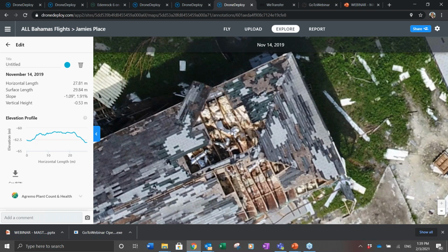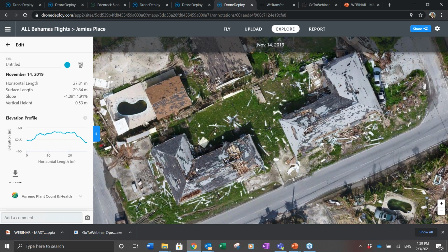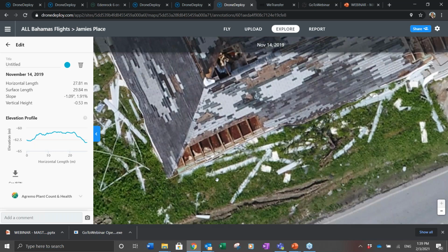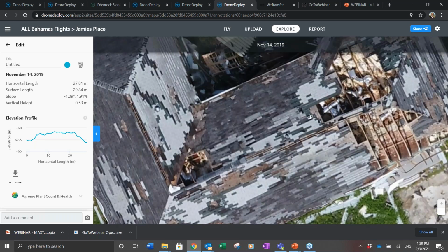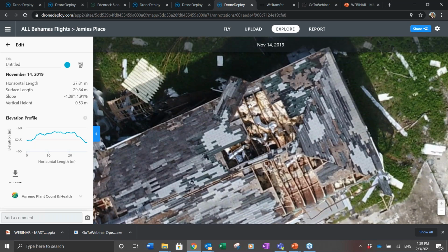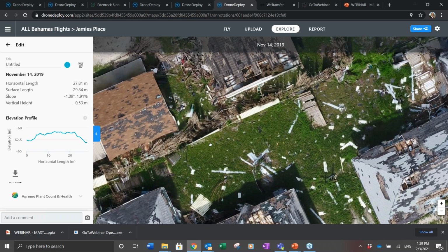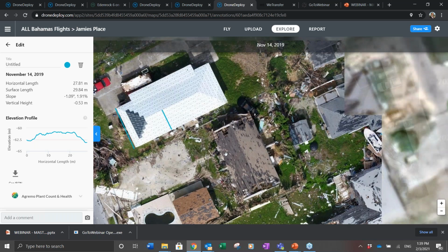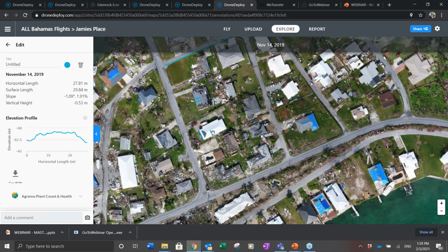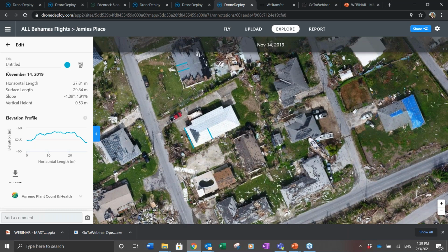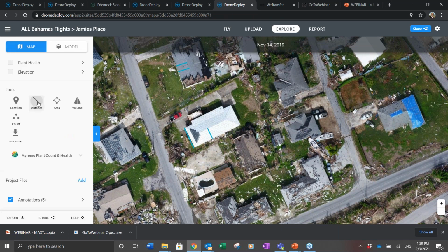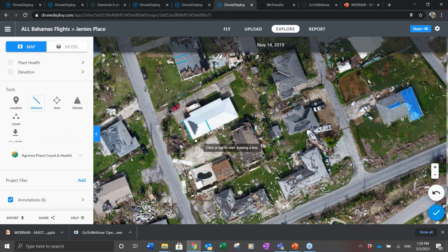Right, so it depends on the lens on the aircraft. You can use, say, a Phantom 4, but you won't get this type of resolution. This particular drone I flew was called a Matrice 210. The optic camera on it had an X5 camera. The cinematic drone we use for origin and cause, one of them is an Inspire 2. The lens on that is unsurpassed. So the details really come down to the lens and the camera that you're using on the drone. We have an extremely high-end system, or several extremely high-end systems. That's how you capture the very high resolution and the ground sample distances.